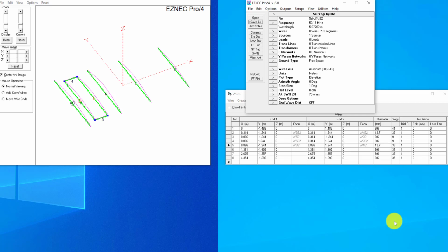So pretty much that's all you need to do, just to take into consideration that with some of the antennas that you'll find, where it's got the element lengths, it will be the whole element length, and you need to halve that, minus part of it in the Y position and plus part in the other Y position, and then you're good to go.